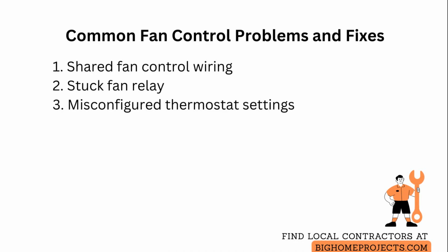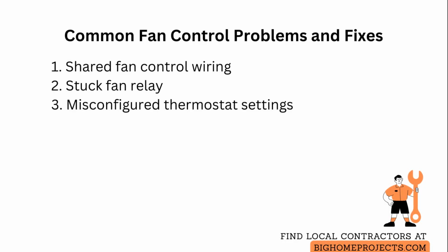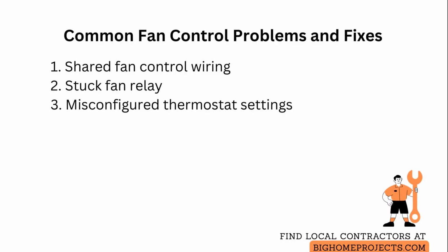For a stuck fan relay causing continuous operation, visually inspect the relay and run a manual control test. Turn power off, tap the relay to free contacts, then replace the relay if it fails to engage cleanly. Relays are inexpensive and simple to swap.